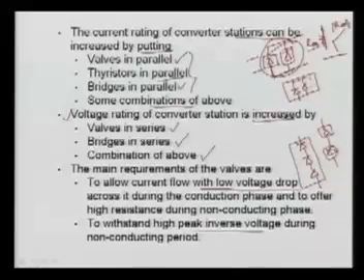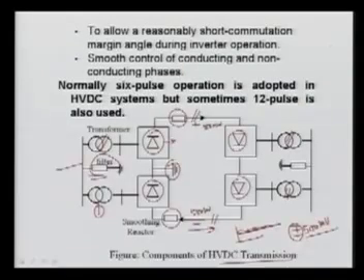Once it is not conducting, we can see a huge voltage appearing across this valve, and it must withstand that high peak inverse voltage during the non-conducting period, because the inverse voltage is appearing across it. If it is not withstanding, it may puncture and get short circuited and damaged. So that creates another problem. So this is another requirement.